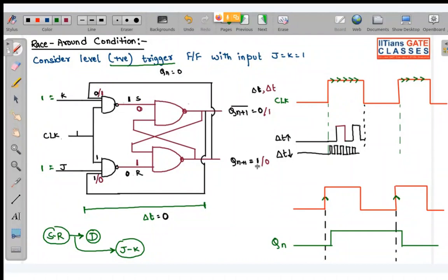You can see why? You can see this 1 has been fed back over here. So again it became 0. Now this 0 will again be fed back over here. This continuous feedback is causing this race around condition. So always remember in life also, if something is a boon at this moment, it doesn't mean that in your entire span of life it will be a boon only. It might become a bane also. You can see the same thing which was actually solving the problem at that very point is now creating a problem for us.